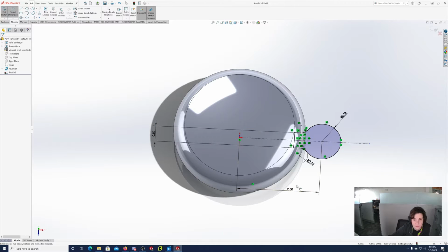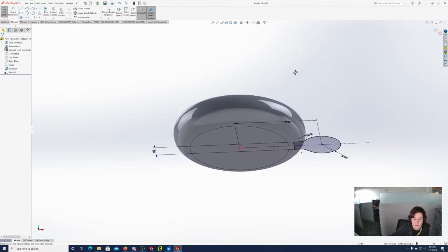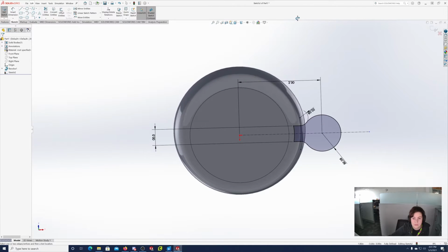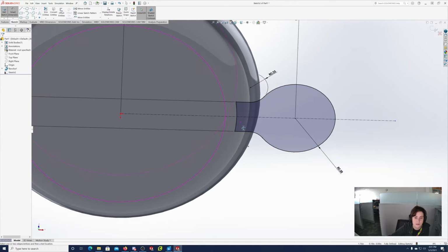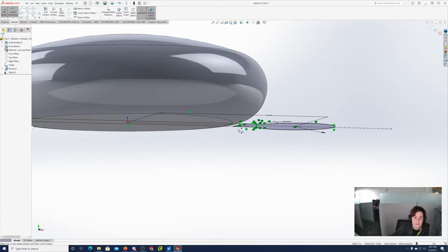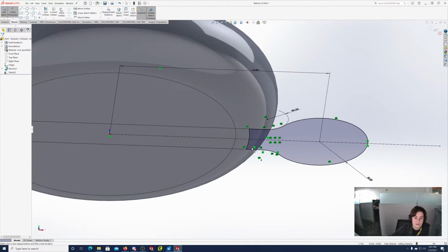So we're going to extrude this shape. And let's see. You know what we did? I used the wrong circle. I've done this before. So see how this arc doesn't quite connect to your shape? So when we extrude this, we're actually going to end up with a gap. We actually want it to go right to this circle here on the bottom, which I messed up. So let's fix that really quick. I'm just going to delete, oops, I've got the dimension tool on. So let's delete that line.